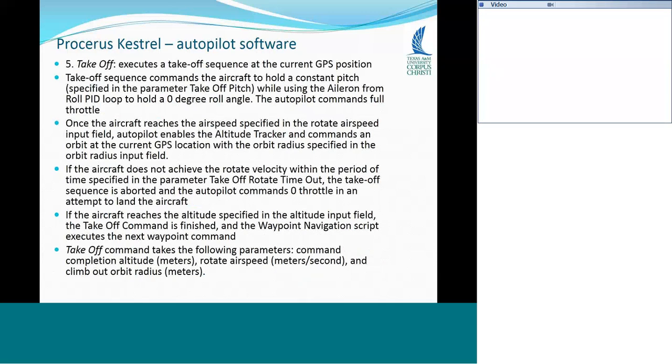Okay, takeoff. Now this is automatic takeoff, and pretty sure this is one of those airplanes where they just throw it in the air. So for the takeoff, there's no XY. It executes the takeoff sequence at the current GPS position, wherever it is.